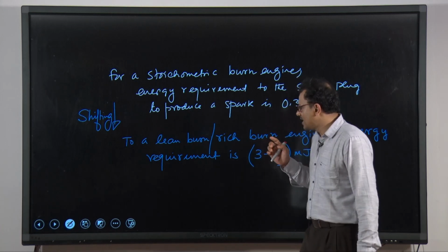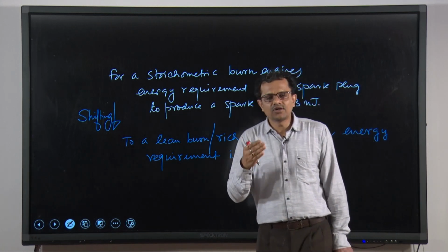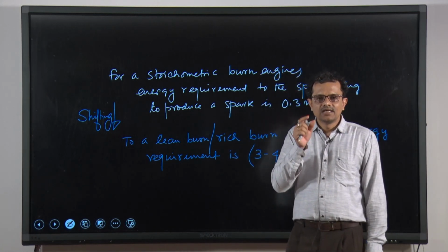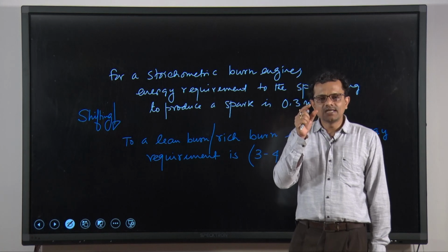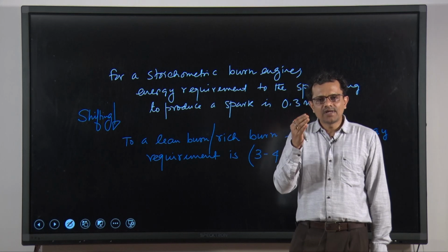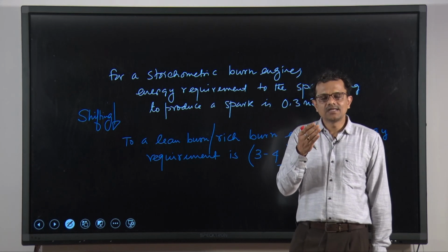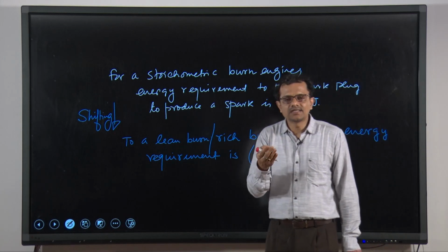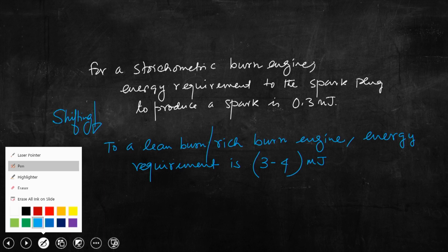If we need to have such advantages, then the opening and closing of the breaker points will not be there. The primary circuit will be activated and deactivated using a sensor, and that sensor is essentially a pulse generator or trigger, right.